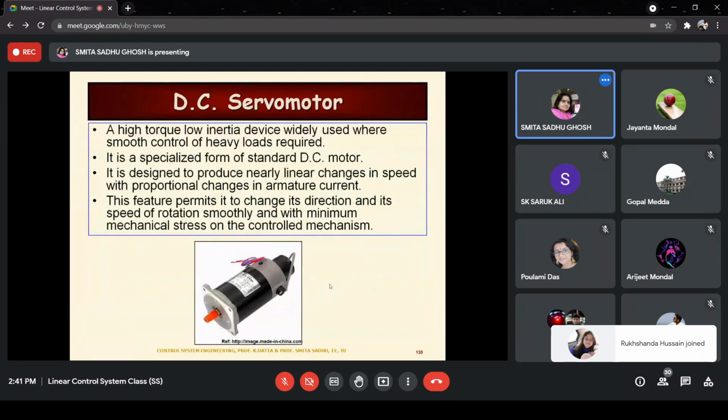Now, as I stated, servo motors are high torque, low inertia devices. So if the requirement is to have high torque but low inertia, let us go through it one criterion at a time. If the motor must have a low inertia, would we go for a motor which has a larger radius or a smaller radius, meaning radius or diameter, whatever you call it? Basically, should the diameter of the motor be large or small for the inertia to be low? Can you tell me that?